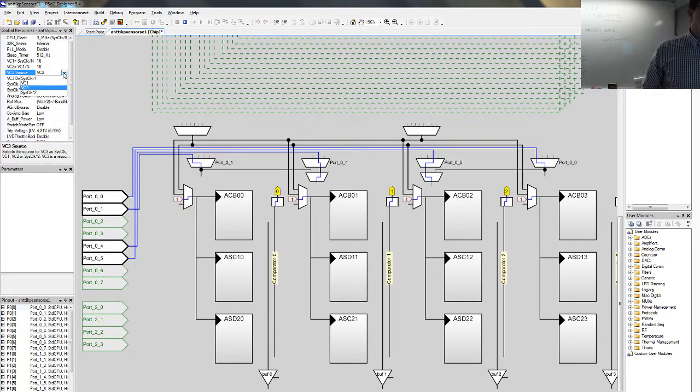If you enable PLL mode, you can have the system clock times 2. So with a 24 megahertz device, you can get a 48 megahertz signal here and divide it, for example, by 3, which you cannot otherwise do. Also some other odd numbers.